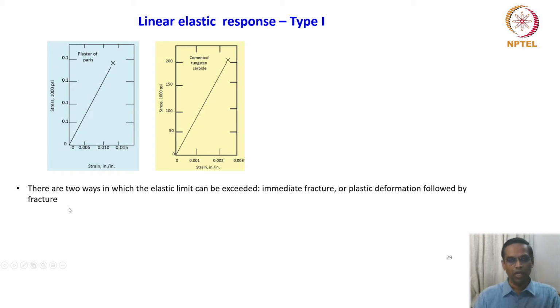fracture. If you recall the previous classes, we always looked at a stress-strain curve as an elastic portion, yield point, and then plastic portion. Right? So here, these kinds of stress-strain curves have neither a yield point nor a plastic portion. So how do we understand this? This is the stress-strain behavior exhibited by a material with almost insignificant plastic deformation. It is highly brittle in nature.